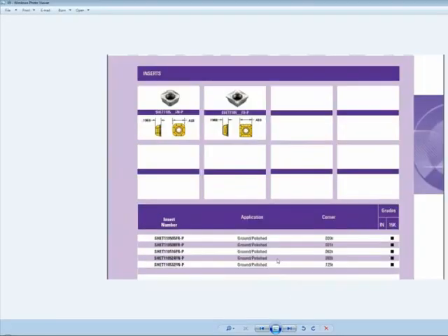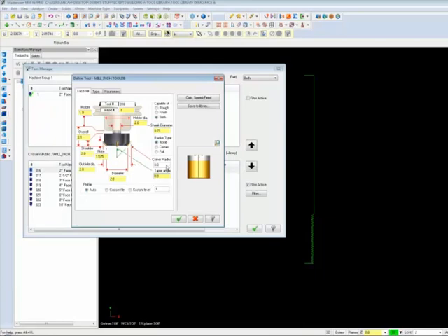Yeah, and if you want to verify and everything, if you want it to work right, you have to have an insert with a radius. So what I think Mike Witten is saying here is that with a 90-degree square corner face mill, you would not define it as a face mill. You would just define it as a bullnosed end mill and add the corner radius that you wanted. Right, see at the bottom now, you get the error. Yeah, unfortunately, that's what you have to do.